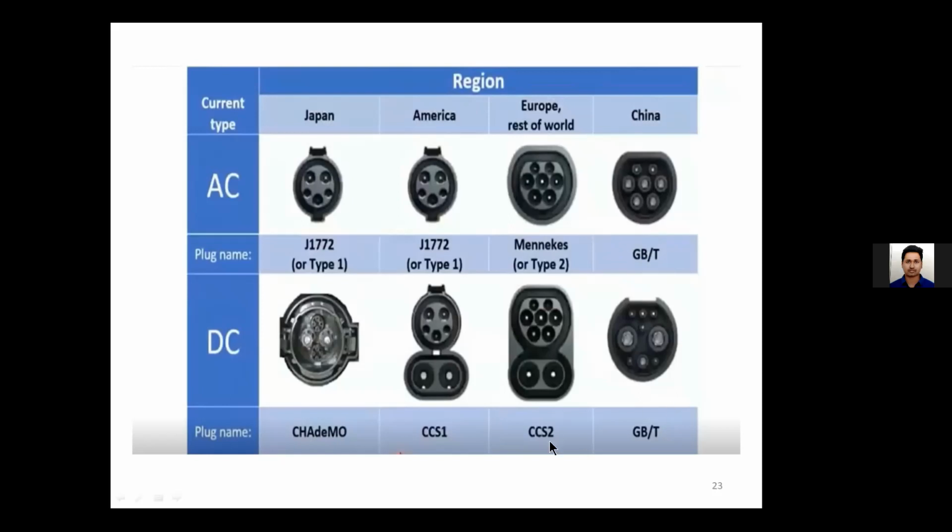I hope you understood the reason behind this, because different vehicles might be using different types of batteries whose voltages may be different, maybe 200 volts or 400 volts, whatever. So whenever we connect to the charging station, some communication happens which estimates the state of the battery. In simple words, we can say it's a handshaking communication signal between the onboard charger and the vehicle.